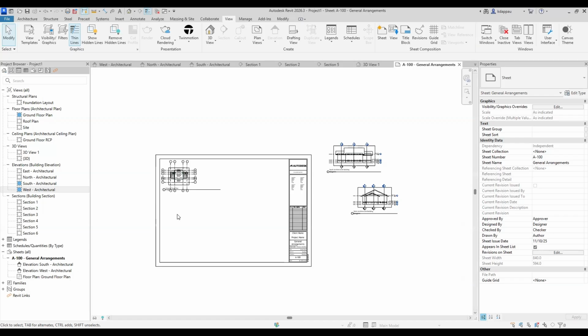So you know that the work I'm doing, I'm going to print it on A3, or on A2, or on A0. Then after that, you bring your view on the sheet. Then when you bring the view, you decide that this view I am putting on this sheet, I want it printed at this scale. It's unfortunate most of us stick to just 1 in 100 and then 1 in 200 for block plan.